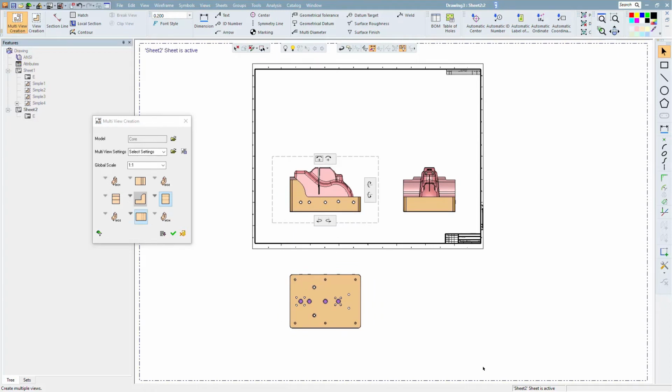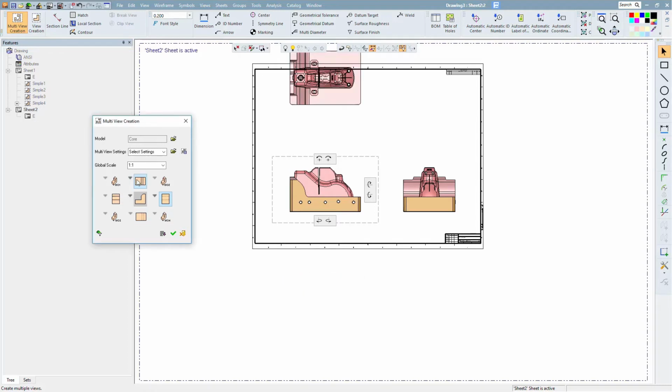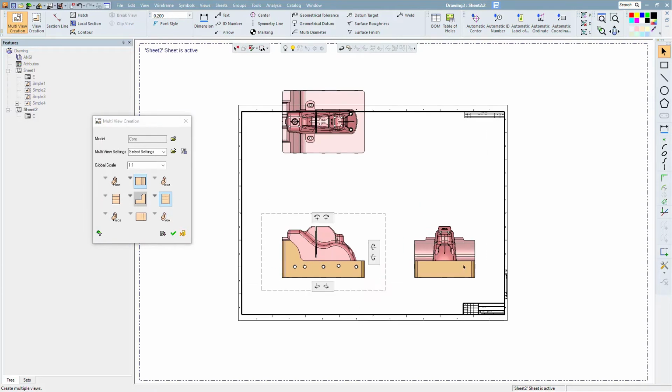The preview is shaded in this mode, but they'll still be made to the attributes like before. And then this area of the dialog helps you set up which views you want in which location. If you have a layout that you're going to use a lot, the thing to do is to save it as your favorite multi-view setting so you don't have to mess with this every time. Also, there's some global control for attributes, so let's go into here, for example, to turn hidden lines on.